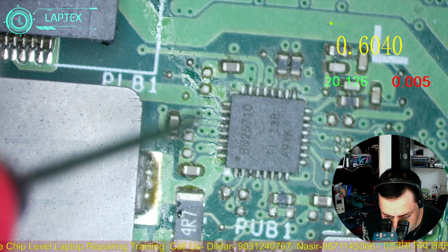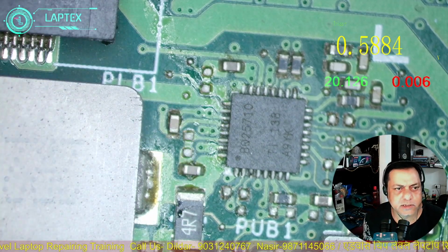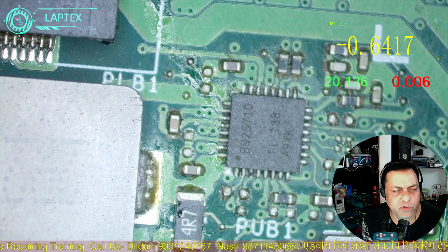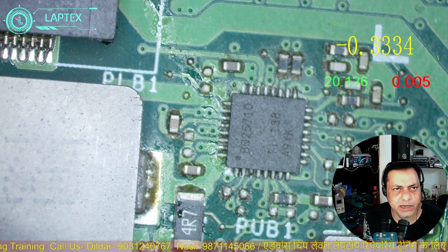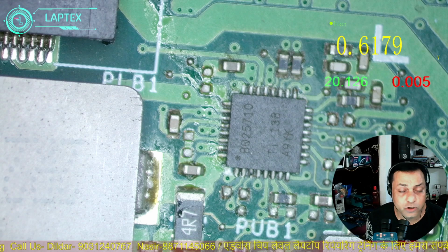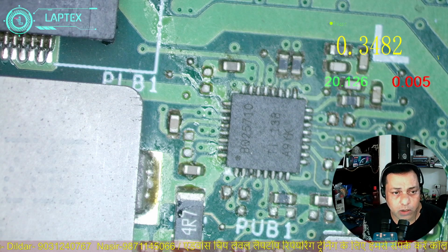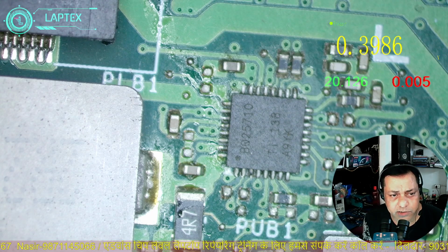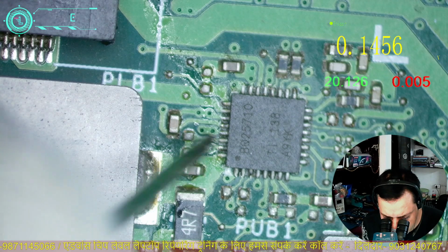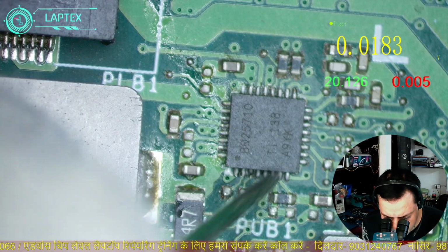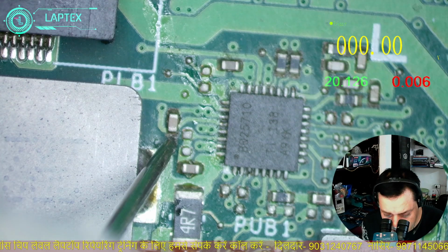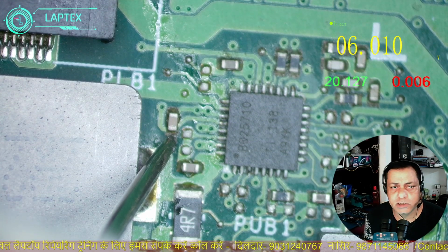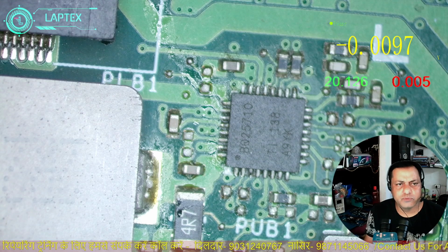Now, if all the things are okay, since there is no AC detect, no AC okay. Why? Because all things are taken care of by the charging IC or by your PD controller IC. So now you have to check whether the REGN LDO is generated or not. Pin number 28 is the REGN. So here 6 volt is available. It means my charging IC is working very well.